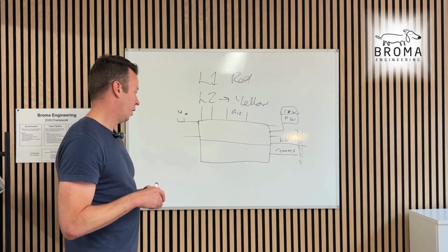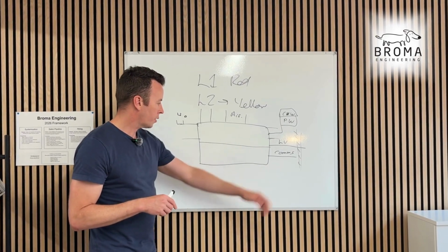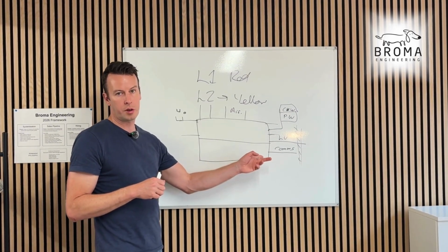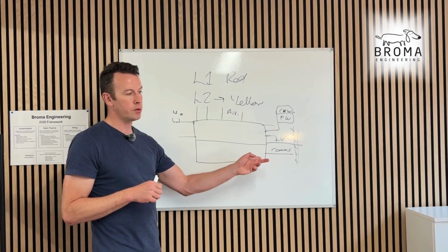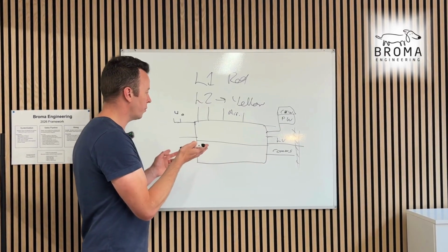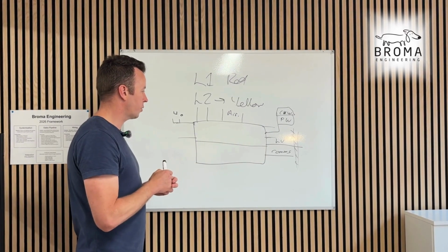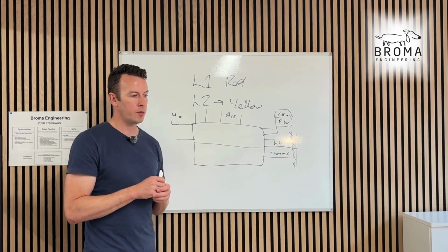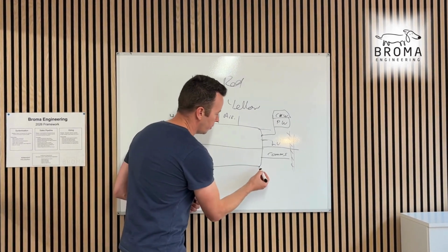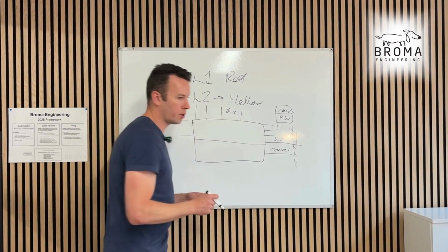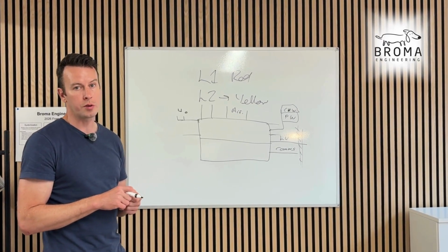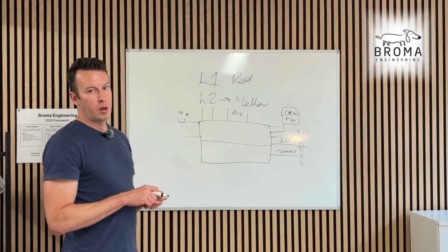Drains as well. Drains should be functioning by now. Check to make sure they're all working. Make sure the AHU isn't going to be sitting on top of a drain. Check that in the model beforehand. Make sure the as-builts are correct. Scan the drains, scan whatever's in the room, and make sure it overlaps on the federated model as it is in real life. Sometimes the drain can be in the wrong position, it'll be under the AHU, and then you're in big trouble. You'll have to dig out the floor, and if you only figure that out when you put the AHU in position, that's not good.